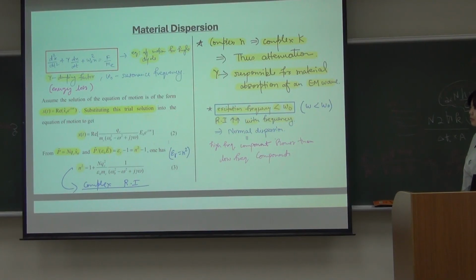Okay, so if my excitation frequency is right here, I can have a very high amplitude. If I match my excitation to the resonant frequency of it, then you see that it's going to swing, continue to add up the energy.